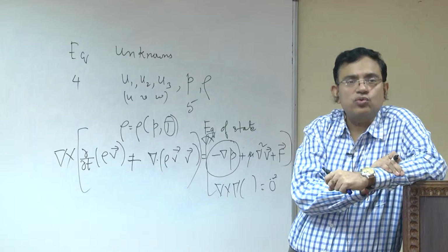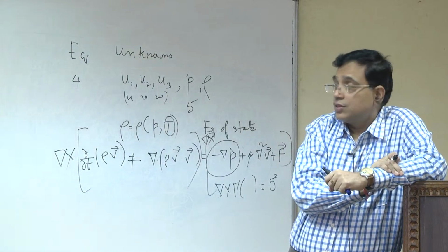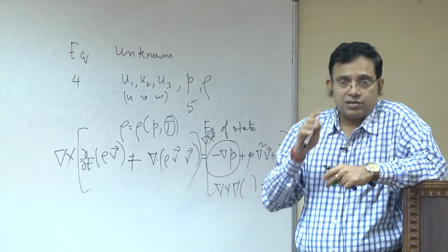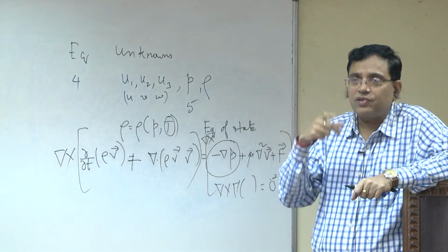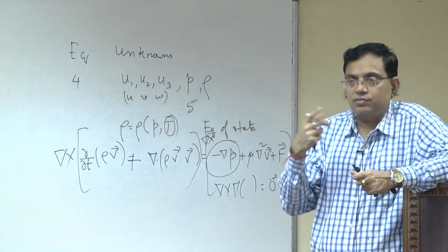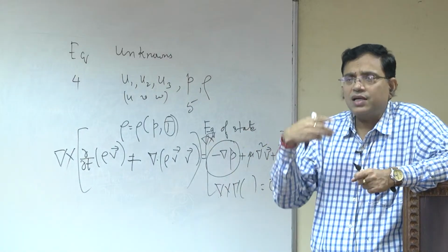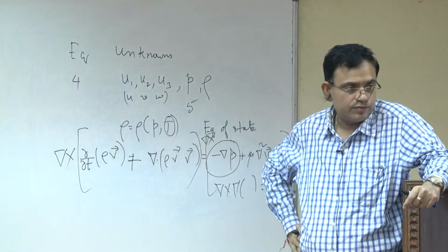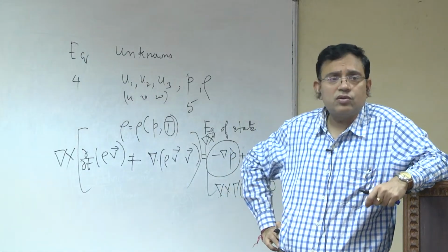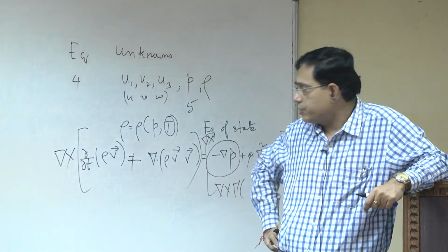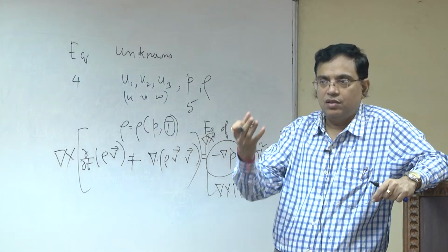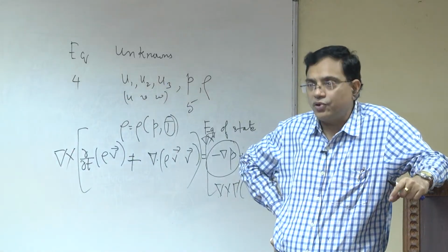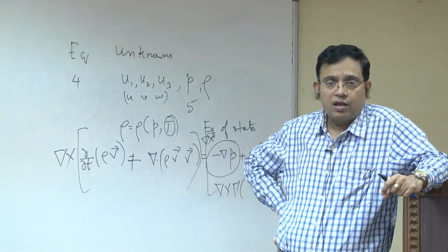So, usually we like to use the primitive variables. What vorticity is doing is giving the advantage of eliminating the pressure, but it brings in the trouble of introducing 2 mathematical functions, vorticity and stream function, not really artificial but derived. So, you have to give boundary conditions on those, which are not naturally defined for a physical system. So, this is not a very good approach for solving all types of problems. Maybe for some problems you can easily describe vorticity and stream function on different boundaries, but it is not quite trivial to do for all. So, this approach is very limited, but it is the intuitive approach.